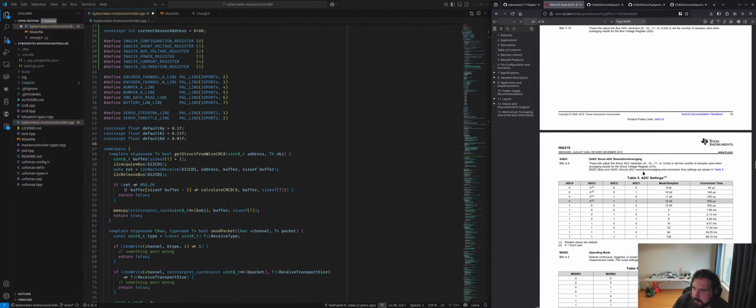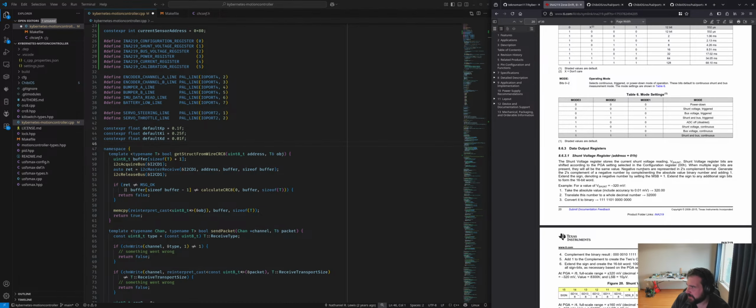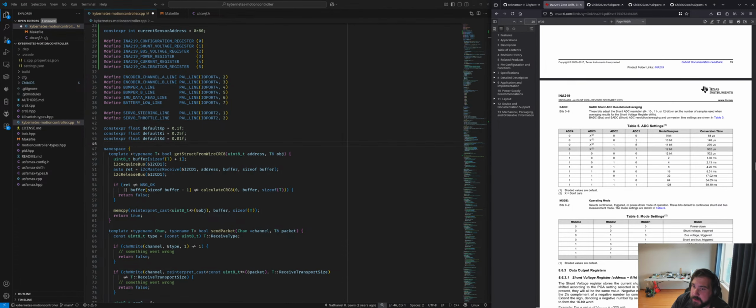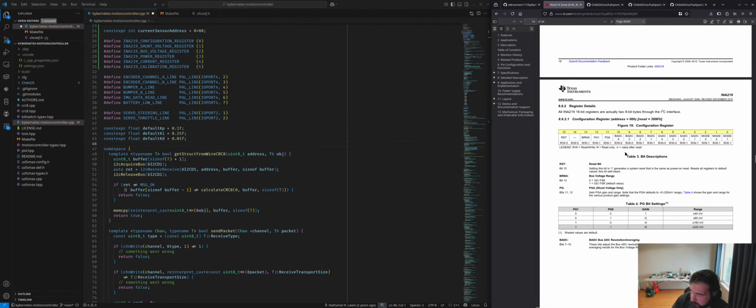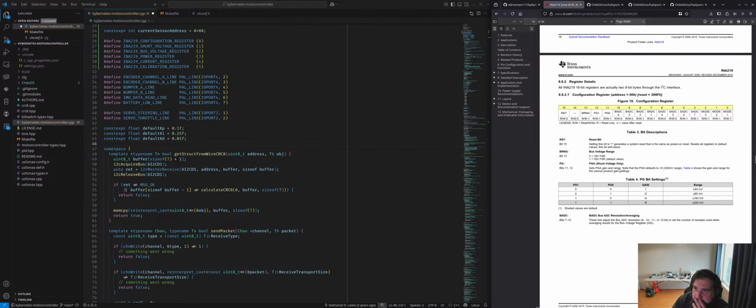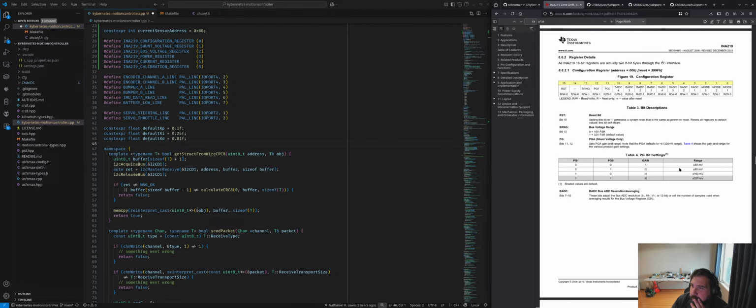There's probably going to be a little... So, I mean, we scrolled past all the math, and I'm pretty sure that all tells us how to compute from our desired system parameters what we should be using here. So, we'll scroll back up here in a bit. Let's just finish reading through this. All right, so both zeros, it's a gain of 1, so plus minus 40 millivolt range. The reason it's plus minus is that this is a bidirectional current sensor.